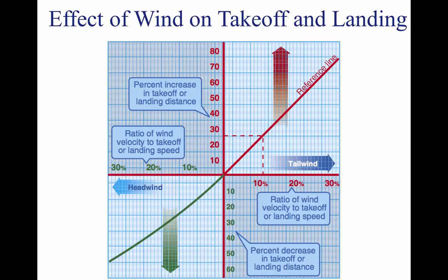The effect of wind on takeoff distance is large, and proper consideration also must be provided when predicting takeoff distance. The effect of a headwind is to allow the aircraft to reach the takeoff speed at a lower ground speed, while the effect of a tailwind is to require the aircraft to achieve a greater ground speed to attain the liftoff speed. The effect of proper takeoff speed is especially important when runway lengths and takeoff distances are critical. The takeoff speeds specified in the AFM-POH are generally the minimum safe speeds at which the aircraft can become airborne.